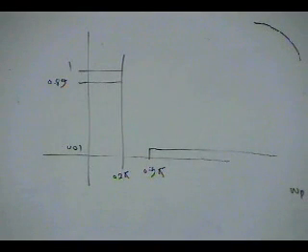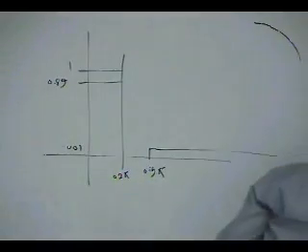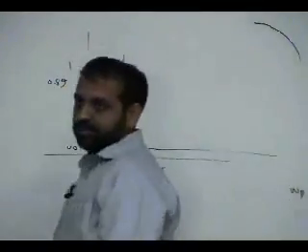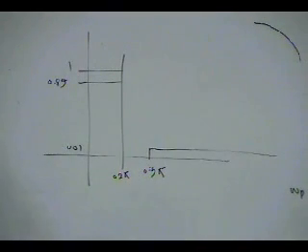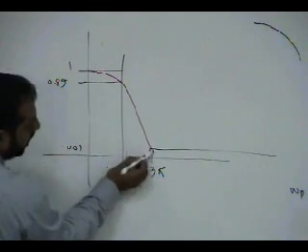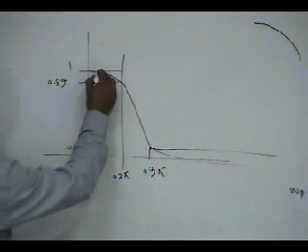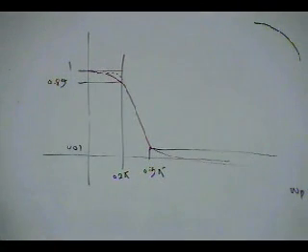Knowing this, I can plot, at least I know 2 or 3 points in the Butterworth. Butterworth is a monotonically decreasing function. So I know for sure that any filter designed to the specification will pass through this point and this point. Any filter which is going above this point is what?